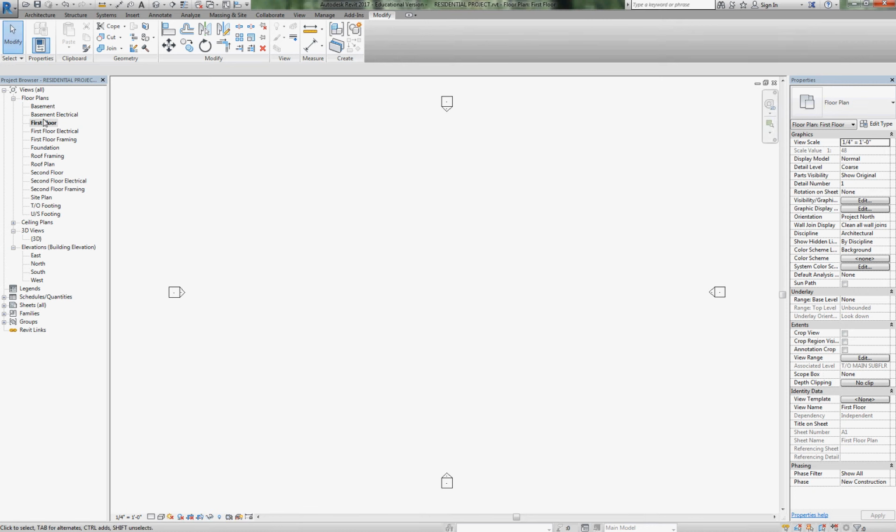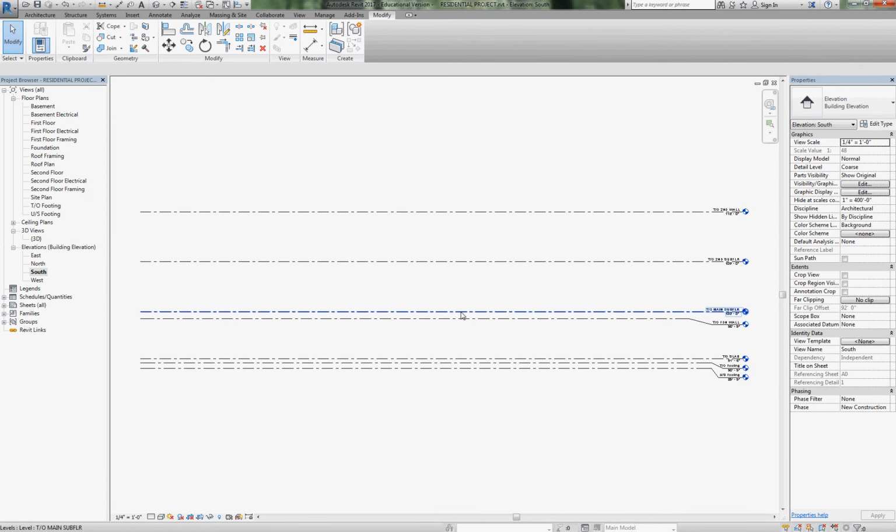we've got multiple windows open, so I go from first floor to south elevation, so multiple views open, there is a button that allows us to close all the hidden views. And so if you do that before you save, you'll get the smallest possible file. So that first save is going to allow us to give the destination.